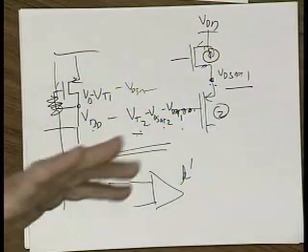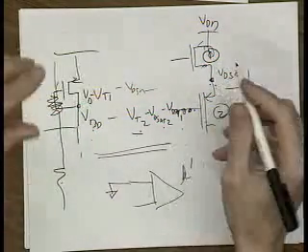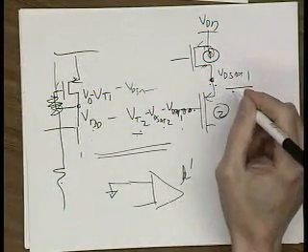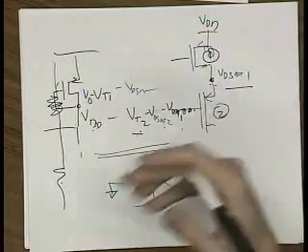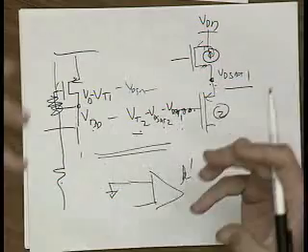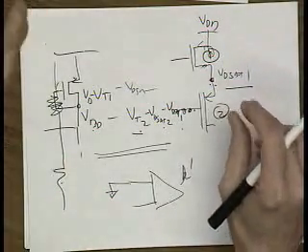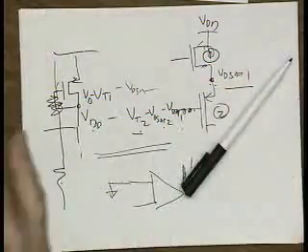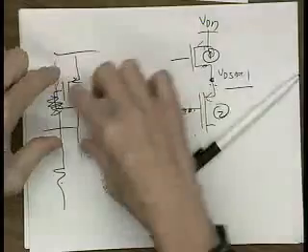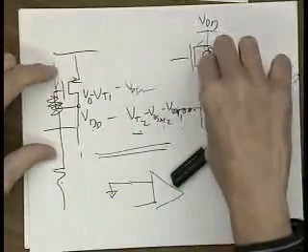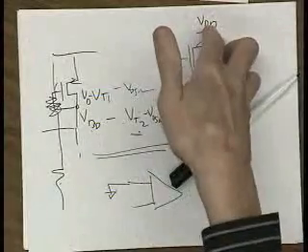Yeah, I mean, this doesn't solve the problem some of you mentioned. Good point. What about the final reference current that you start this whole thing from? That's a function of a resistor and some VTs and so on. Yeah, that's true, and that doesn't solve that problem. It's just a matter of making sure that all the VTs cancel out. There's a replica of these VTs in your circuit, but there's a reference current that's establishing the reference currents for this and for this as well.